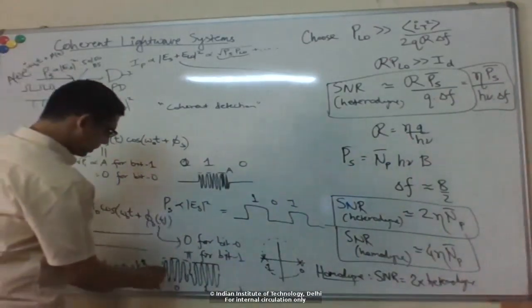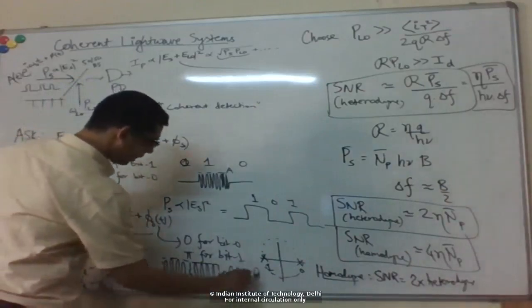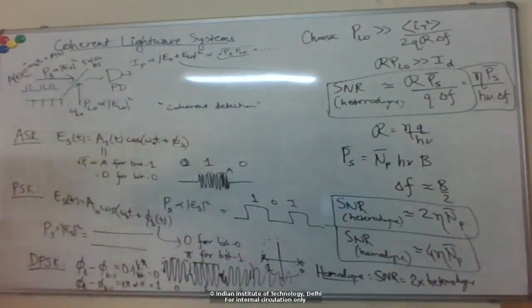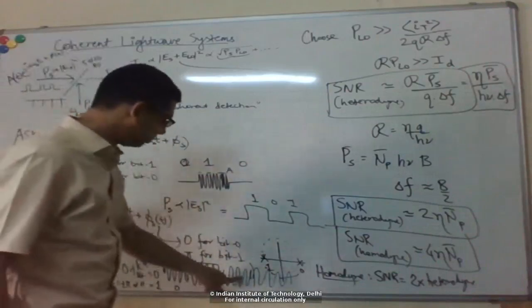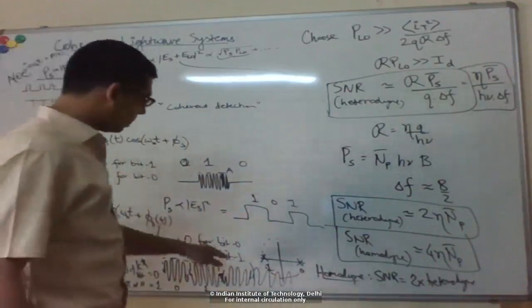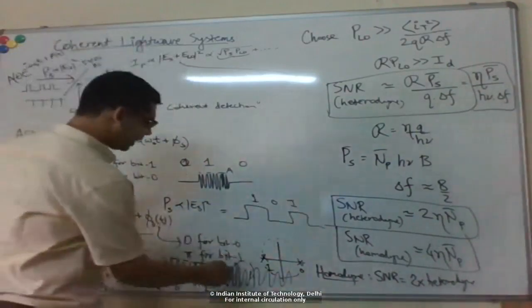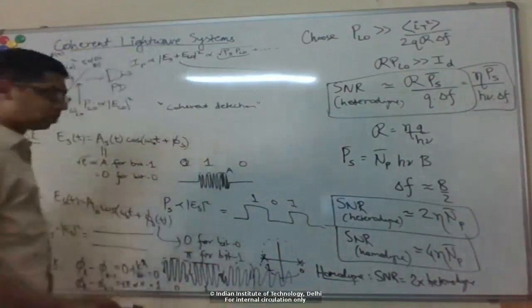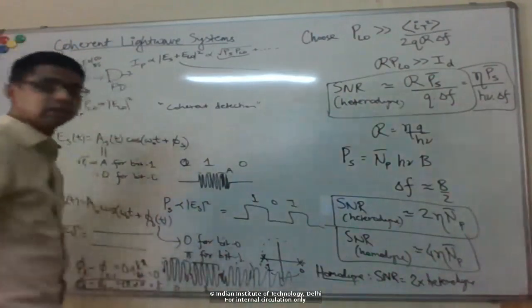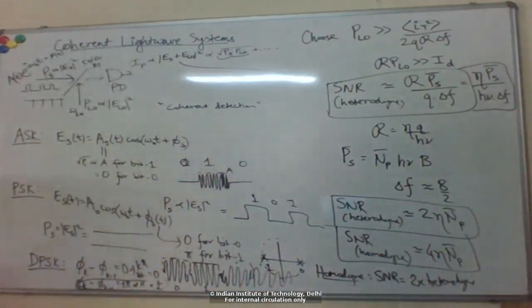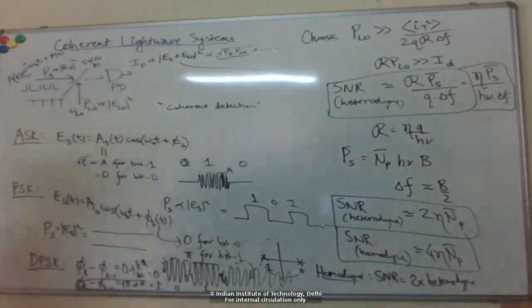So, for example, let's say you measure these 2 bits, and then there was a phase jump, and now the next 2 bits. After the phase jump, let's say at the transmitter I had sent 0, but now at the receiver I have pi, right? Because the phase has jumped, 0 became pi and pi will become 0. So if at the transmitter I send 0 and pi, at the receiver I get pi and 0, but I still decode the bit correctly, right? Because the information is in the change in the phase from bit to bit. Similarly, if you send 0 0, you receive pi pi, and again your recovered bit is correct.